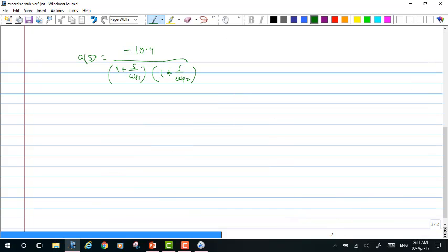Since our omega P1 frequency is far lesser than the value of omega P2, the omega P1 would act as a kind of dominant pole, right? Now let us visualize the magnitude plot of this open loop transfer function. So what we have is a kind of open loop, okay? So A of j omega over the y-axis, and that's being denoted in terms of dB, and we have an x-axis having the frequency in terms of log scale, okay?